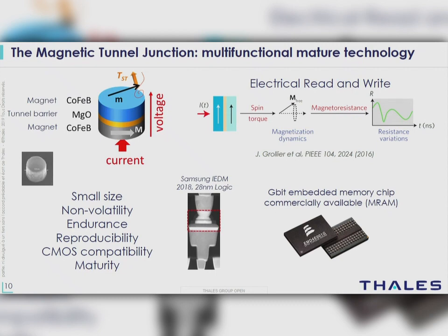And compared to, so I think here everyone is sold on spintronics, but compared to other nano devices such as memristive technology, the huge advantage that we have is a much higher reproducibility and a much higher endurance of the device, because we are doing purely physical phenomena. When you turn the magnetization, you're not damaging the devices. So we have higher reproducibility, higher cyclability, higher predictability compared to other technologies. These are arguments that you can give memristor people if you meet them.